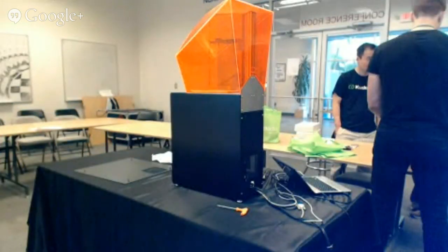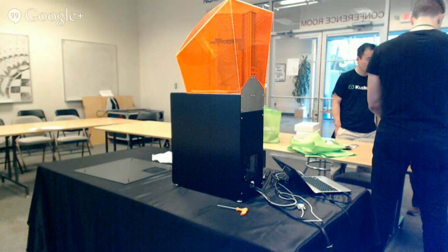This was the first edge I put in. I made it too sharp. That made it hard to hold on to the rest of it. This sharpening edge is necessary. This slope is enough. So I get stuff here, right? I don't need to go this much. I don't need that. I don't need this much slope. So this first, I have way more slope than I really need. And that made this edge too sharp. Having this edge too sharp made it too hard to hold on to the piece for the rest of it. So then they got all messed up.